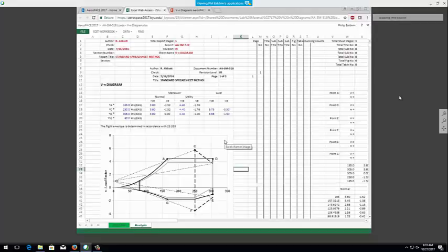And so if you have a very weak throw, you can compensate with a higher CL max and a lower wing loading, although there comes a point where that starts to not actually help, because it's increasing your induced drag. And so it turns out aspect ratio, CD0, e, and even the propeller pitch to diameter ratio, these are relatively flat. Your launch is dominated by this velocity, CL max, and wing loading, which is not entirely surprising. And then we have this kind of threshold effect. It doesn't go below a certain level.